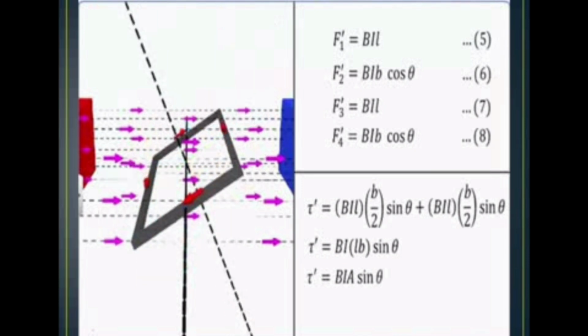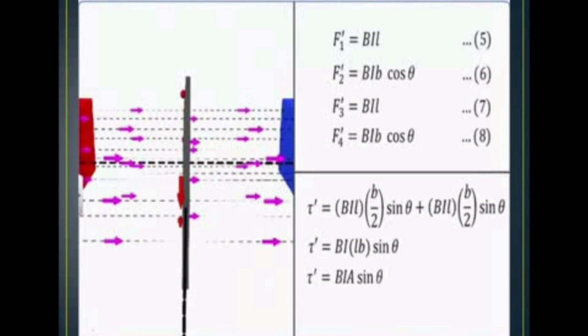So that's the torque of the coil. The coil is rotating like this. Suppose this coil is like this, what will happen? The coil is perpendicular to the magnetic field. This is one complete rotation. The force is acting in the downward direction. Theta becomes 0. Sin theta 0 means the total torque becomes 0. See, the force is acting like this, in the downward direction, torque tau dash equals 0. Sin 0, the total torque is 0. So it is parallel to the magnetic field. The two sides being parallel to the magnetic field means the torque becomes 0.